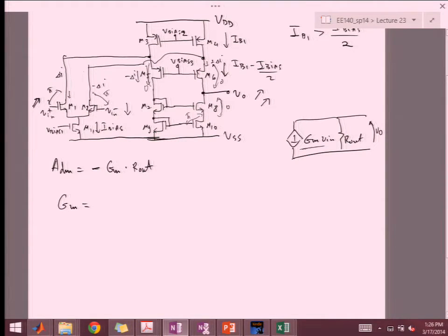And the rest of this circuit is just a current mirror, right? So it will essentially take this delta I and move it to the output. So it's really not doing anything to that current except mirroring it. Therefore, the only thing that really converted voltage to current was this GM1, right? And because we're referring to this input, it's minus GM1, because my overall polarity is positive, right?